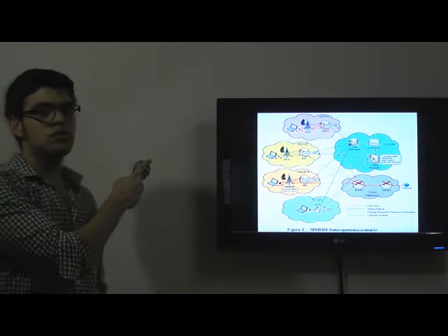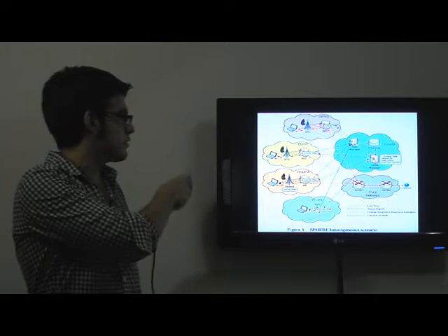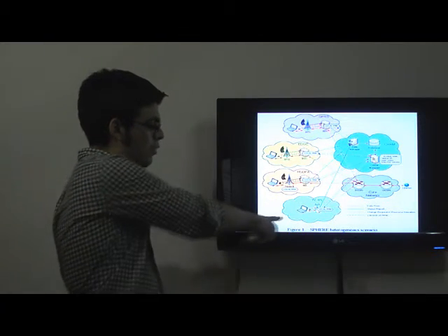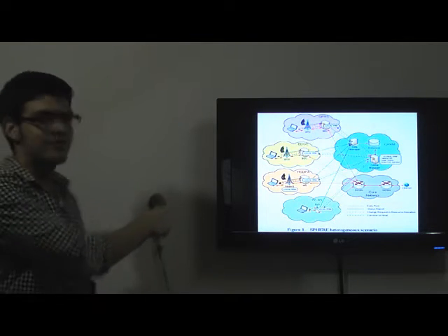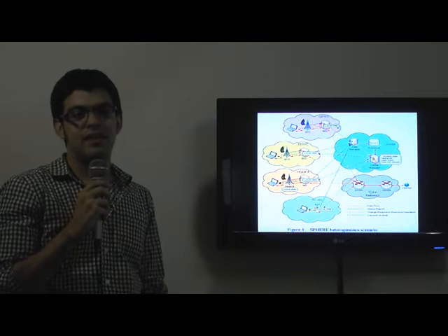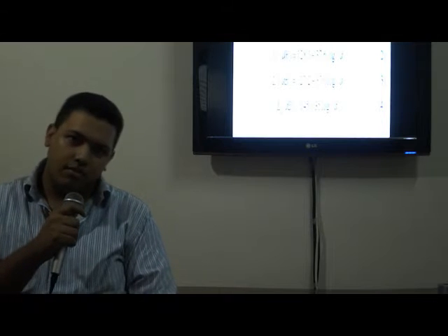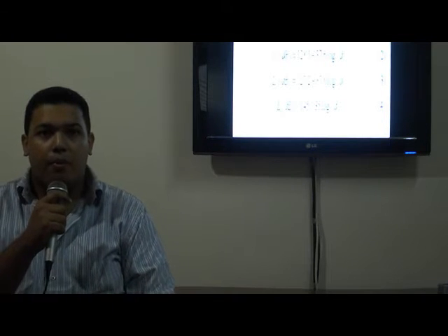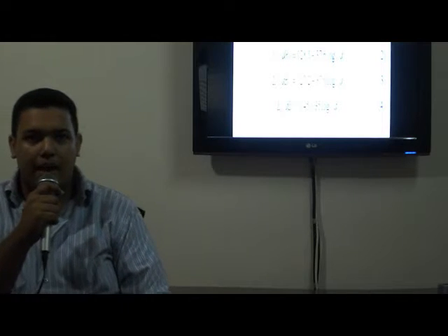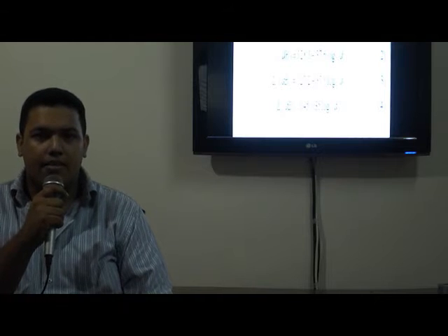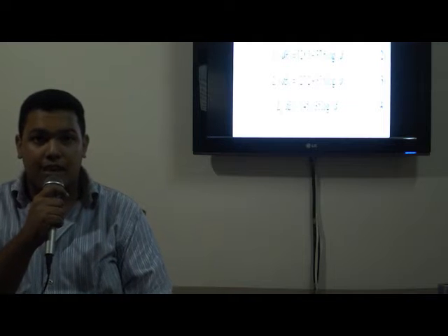Figure 1 shows the scenario modeled by the Sphere platform, which includes the GPRS, EDGE, HSDPA, and wireless LAN radio interfaces. The entity directly collects specific RAT information. Now I'll be talking about the radio link model. This module models the radio propagation condition between transmitter and receiver, and is a generic entity employed by any wireless link established. It characterizes the 3 radio propagation effects, namely path loss, shadowing, and fast fading.